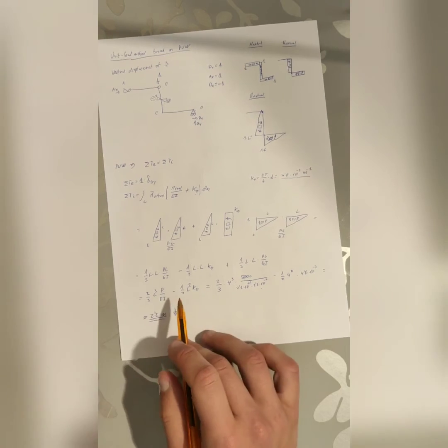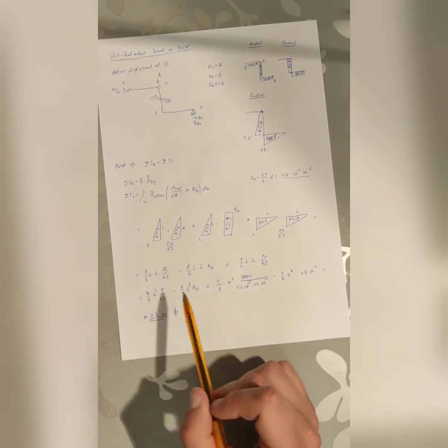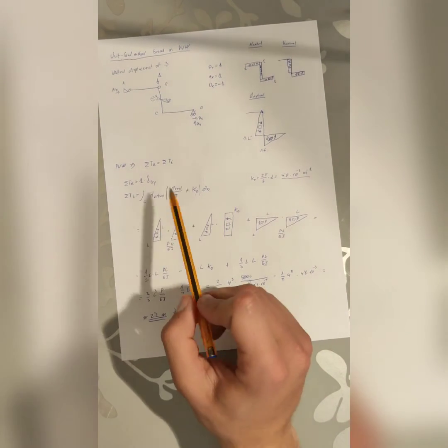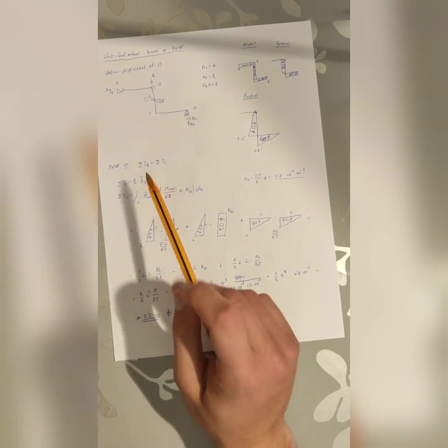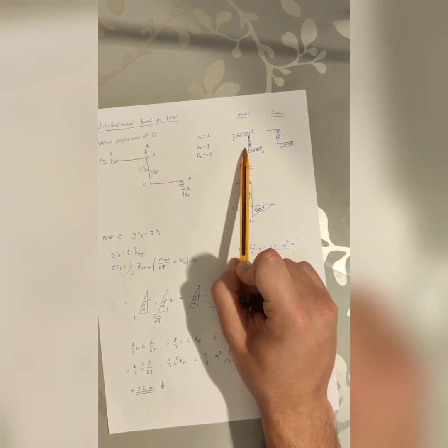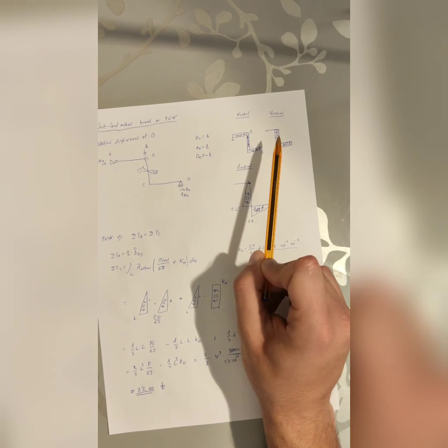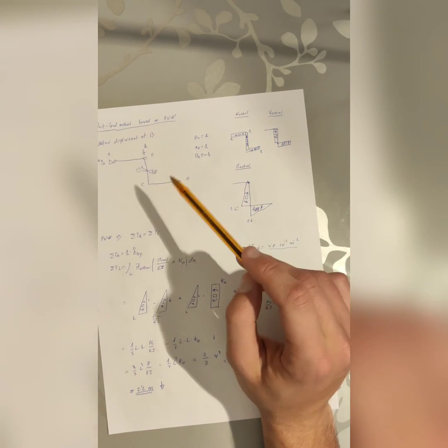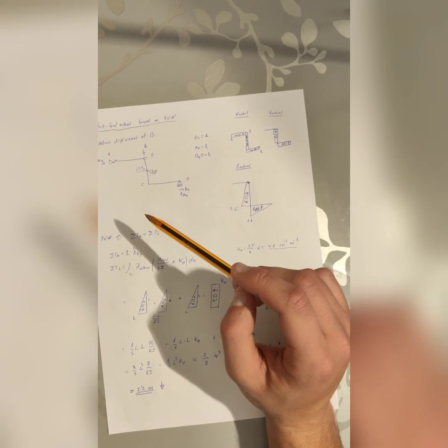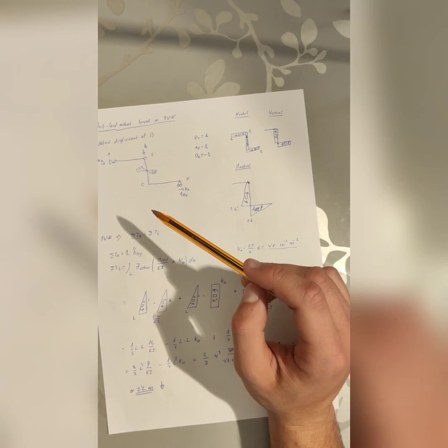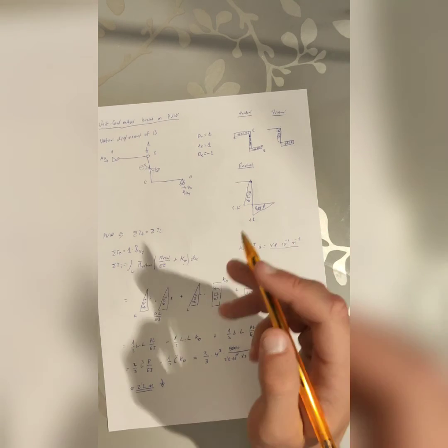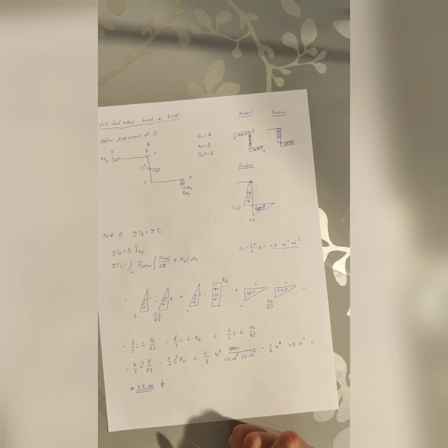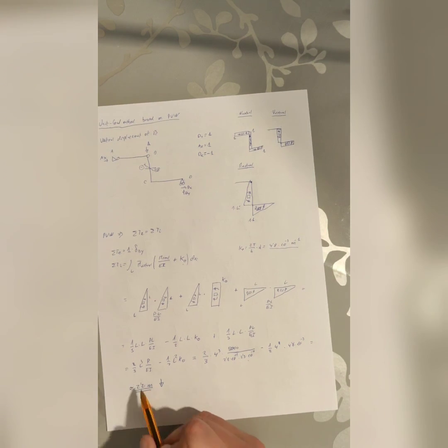The reason for this difference in the values is the fact that we only take into account moments. For us, the axial force and the virtual force do not create any displacement, since the longitudinal and shear moduli are infinite. Therefore, we can say that this approximation is good and take this value as the displacement at B.